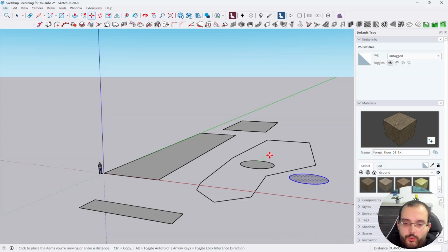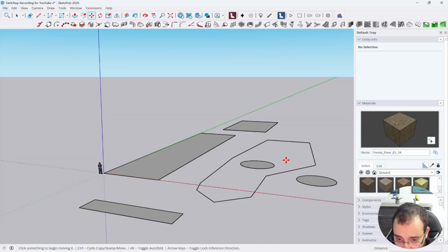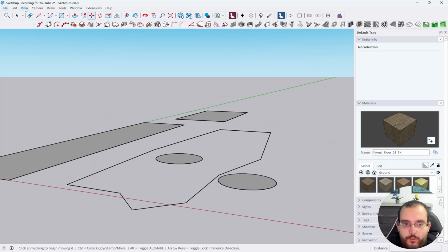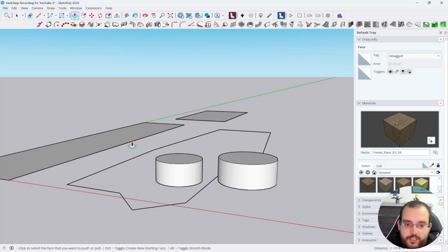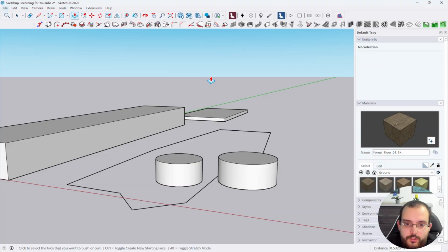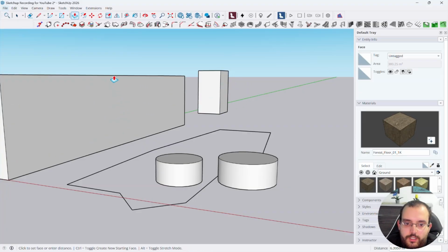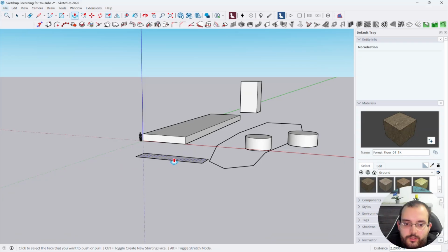And obviously, if you don't want to move this, you can just press the escape key. That's it. Now, let's say I want push and pull. So instead of clicking on that, you press P. Now I can select any shape I want. I can go like this, like that, and all that good stuff. Obviously you can't do that here because that's not a flat surface, sorry. So just like this, all that good stuff.